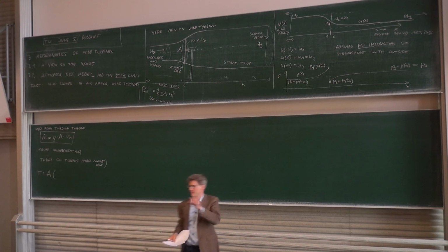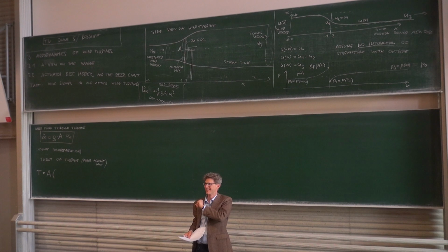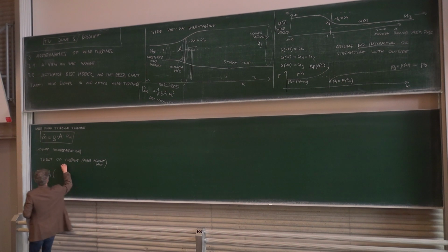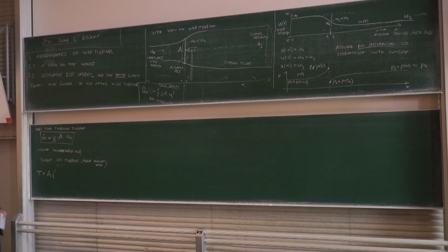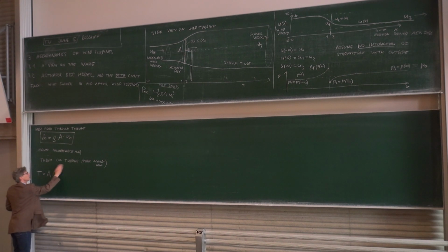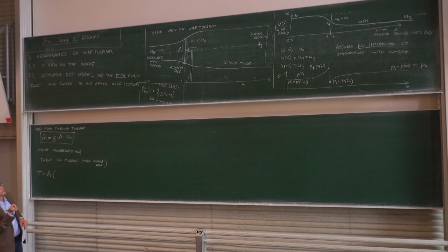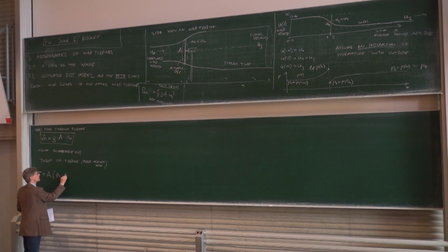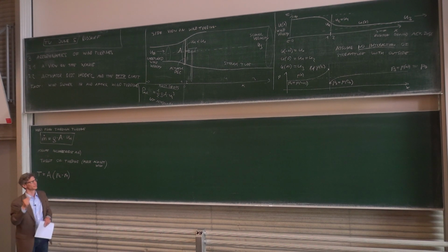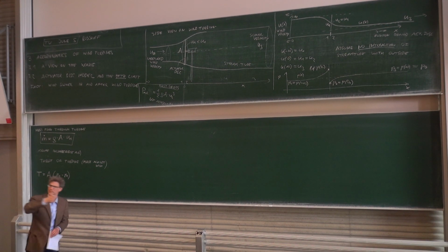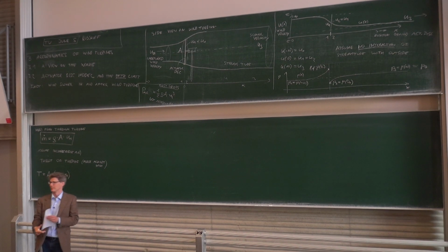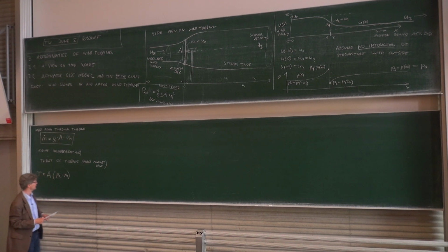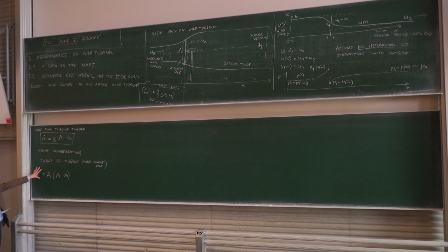When I write symbols here, I just keep track that they are positive. So you think of the sign. It's the force against the wind in this direction. So what is this force? It will be P2 minus P1. This difference, and then I have a positive number, and this number is, if you regard the wind turbine, the force that pushes against the tower in that direction. If you regard the wind field, it's the force that pushes the wind field in that direction, because they need to be equal. So this would be the first formula, the thrust of the turbine.